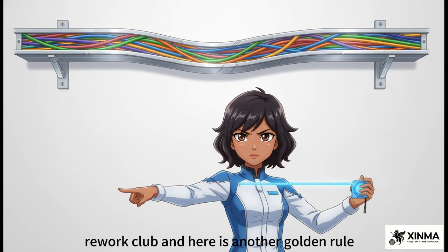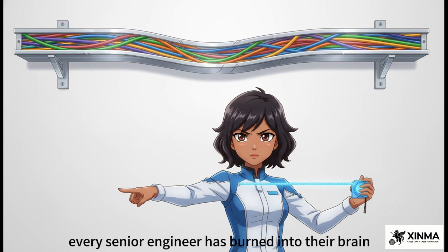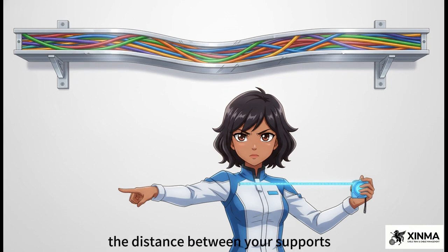And here is another golden rule every senior engineer has burned into their brain. The distance between your supports absolutely governs your overall load class. Honestly, it doesn't matter how incredibly strong your steel tray is. If your supports are spaced too far apart, the whole system is going to sag, buckle, and eventually fail.